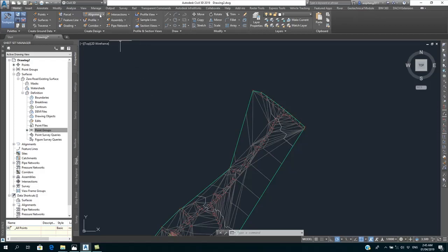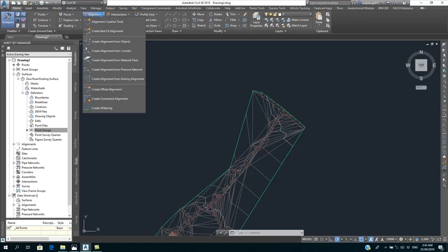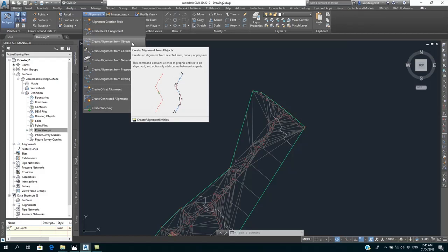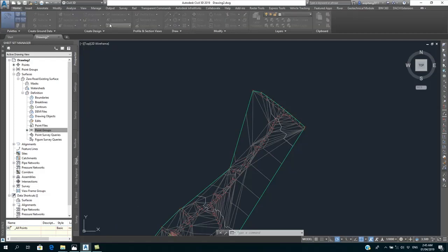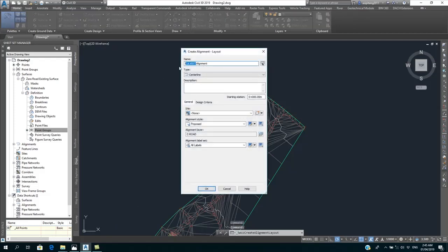And to create your alignment, you can use existing polylines that define the alignment as an object. So for instance, in estate development, they already define the layout, define those lines. So those lines can be used as an object and converted to alignment. And also you can create an object for yourself. But if you are working on terrain where you don't define such, then you need to specify alignment creation to define the road alignment with respect to the design speed, and you have to follow the criteria standard.